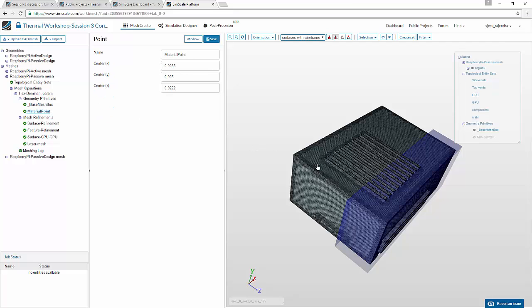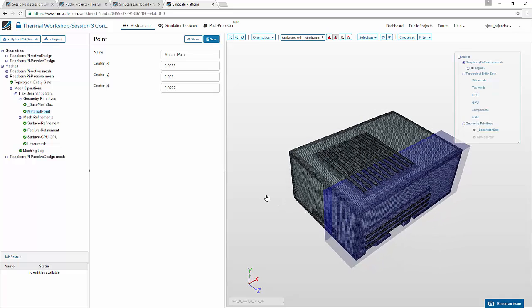And material point is one which decides where your mesh is. So we have something called an internal mesh and an external mesh. External mesh is for aerodynamic purposes usually. So in this case, you create the geometry, which is the car or an aeroplane, say for example, but you want the air domain, which is everything other than this car or the aeroplane.